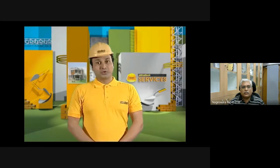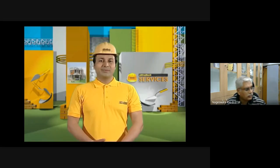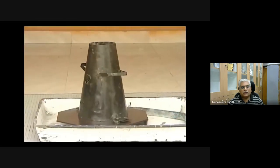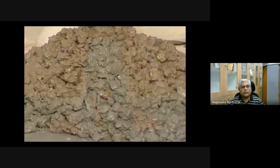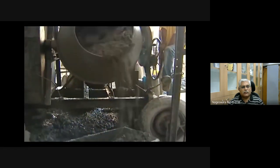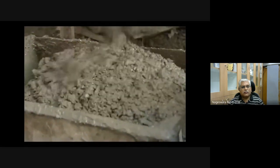The ease with which one can work with concrete is called workability. This can be measured using a simple test called the Slump Test. Let me show you the procedure. The slump cone test is a simple and popular test extensively used at sites to assess the workability of the concrete mix. The test should be conducted at the commencement of the concreting operations or whenever the workability of the concrete changes.